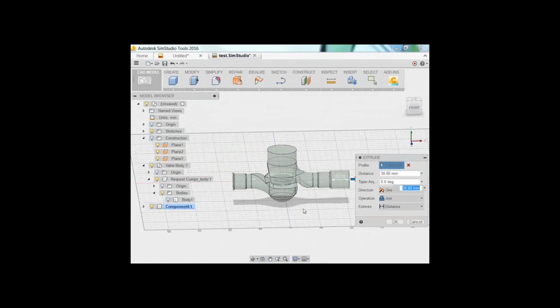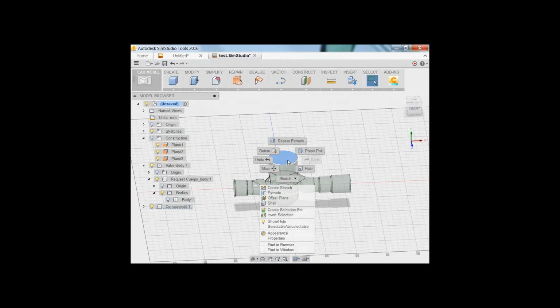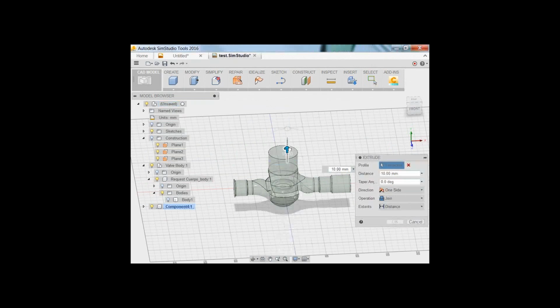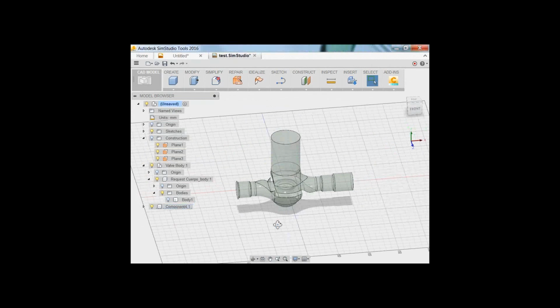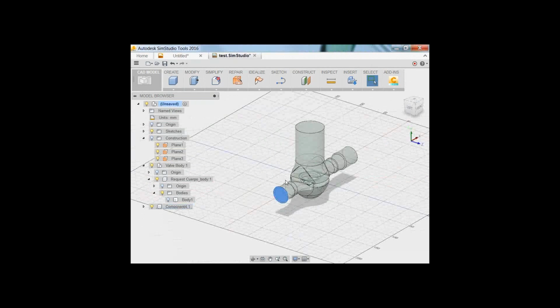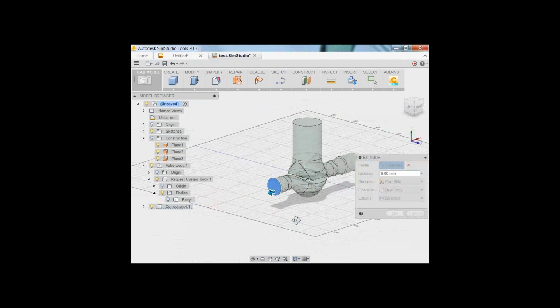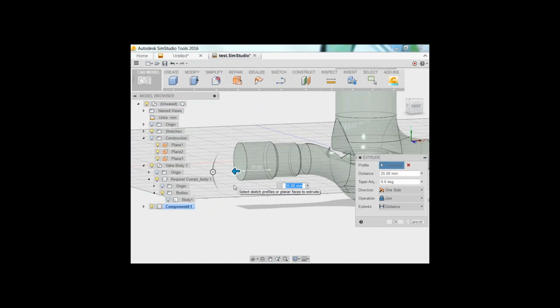It also matters for the edges. If this was a model with heat transfer and I have a temperature boundary condition where the outside of the surface I'm applying it to is actually touching the solid body, then I'm going to have an artificial conduction from that outside edge of my surface. So I always want my fluid volumes to be extended away from my solid bodies.